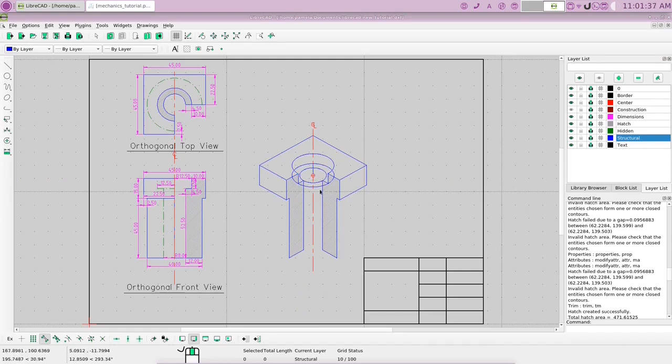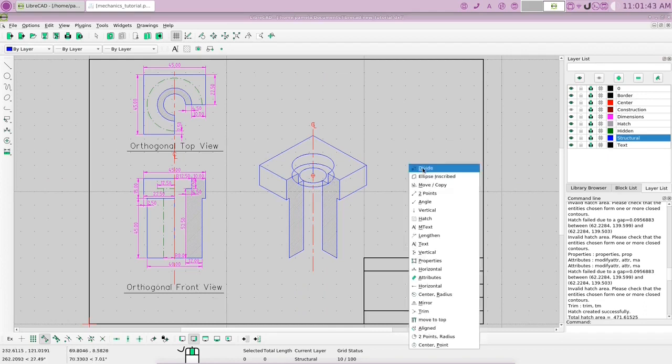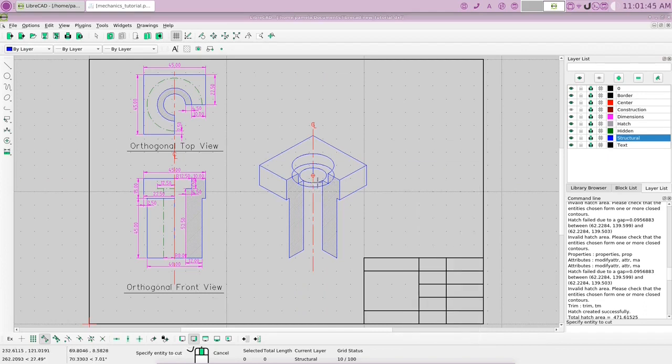Okay, now let's look at these other ones here. Okay, let's go back to the divide. Let's highlight the circle to divide, and on endpoint right at that line, select it again, and on endpoint at that line. Okay, now highlight the piece we're going to remove, hit the delete key, it's gone. Now you can see we have this line here, okay, this circle here.